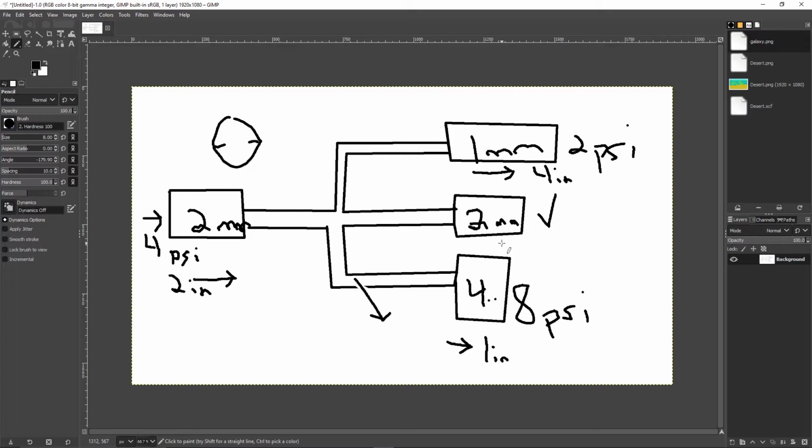So specifically today with the clutch, if your clutch is acting funny and we suspect something is wrong, the first easiest thing that you need to check is to make sure that the hydraulic circuit is working as intended. And this slave cylinder is mounted most of the time on the outside of the transmission.